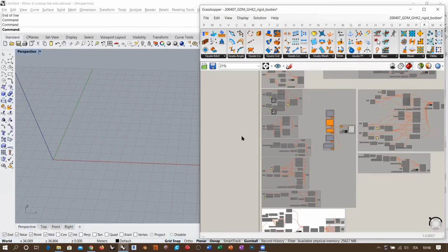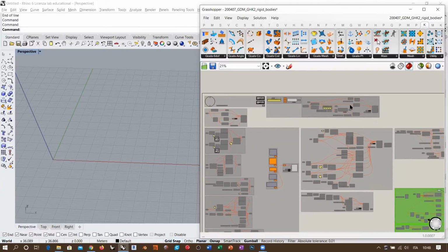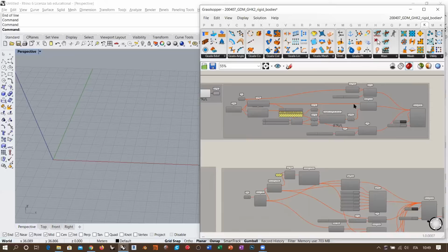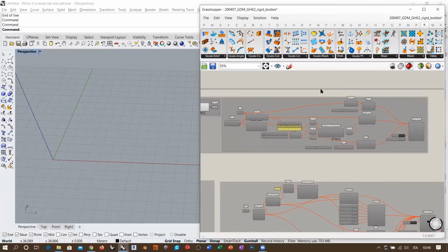And actually, you will see the potential that this beam has, which is basically substituting the whole problem that we were discussing here. Because what we were doing here was representing a very rigid body using an elastic body. So we would be pushing the elastic strength and all the remaining forces to the limit, and that's why Kangaroo becomes very, very slow.